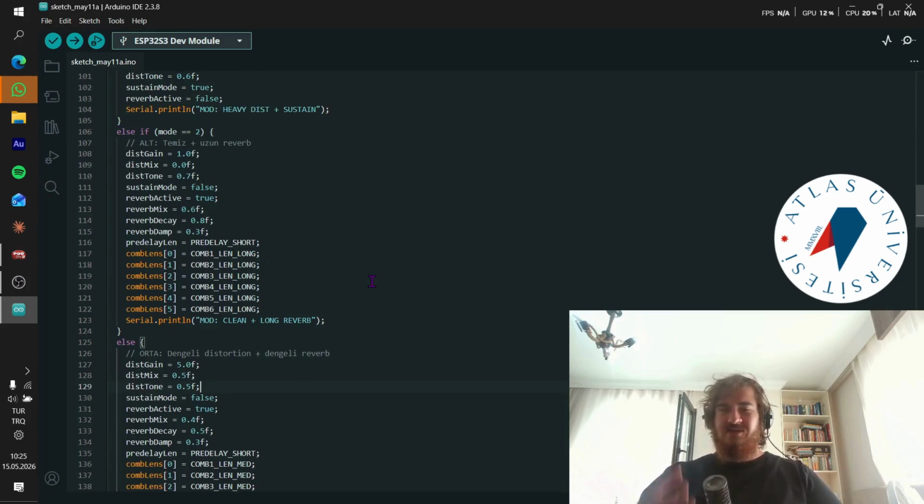So it has 3 pins. One is for first location, one is for third location, and middle one is common. So I'm putting 3.3 volts common, and if I switch it to this position, then it's going to there. If I switch it to this position, it's going to there. And for the middle position, you shouldn't read anything, so it's better to use this one, because you will use less pins.